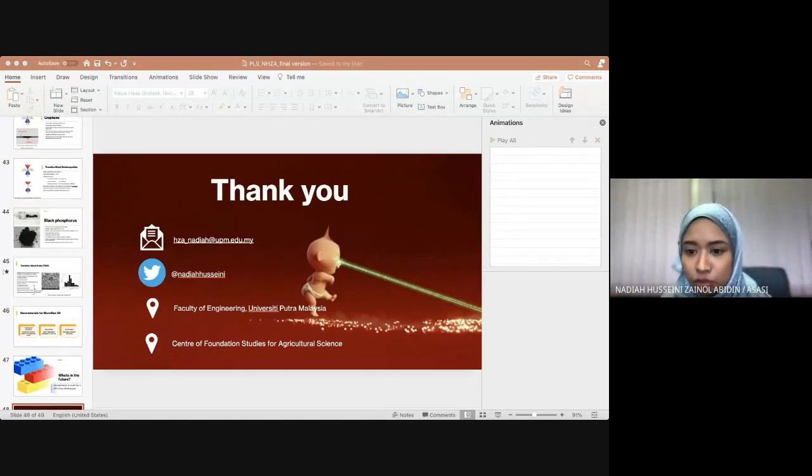How can we control the band gap of TMDC while using the mechanical exfoliation technique? Okay, so I told you with mechanical exfoliation you can actually control the number of layers, right? For each thickness you have to characterize it for its band gap. So that is how you get to know what your band gap actually is.